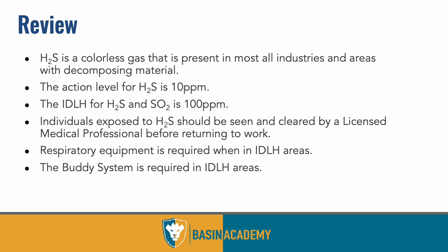IDLH for H₂S and SO2 are 100 parts per million. Individuals that are exposed to H₂S at any level above the PEL, which again is 10, need to be seen by a medical professional immediately. Respirator equipment, meaning full face piece respirator equipment and self-contained auxiliary breathing air supply, must be available and used by workers at over 100 parts per million, otherwise known as immediately dangerous to life and health, or IDLH. And the buddy system is also required in IDLH atmospheres at 100 parts per million or more.